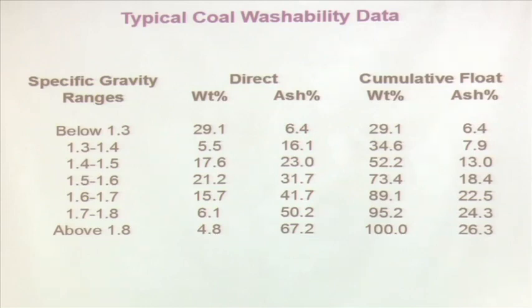So, what have we done? Basically, we have got a density distribution, and along with that a quality distribution. Okay. Now, what can we do? Now, steel plant people, suppose this is a coking coal. Steel plants need 18% ash. Okay. So, what can we do? If I want 18% ash, how much material will be sellable? Suppose I start with 100 tons of material.